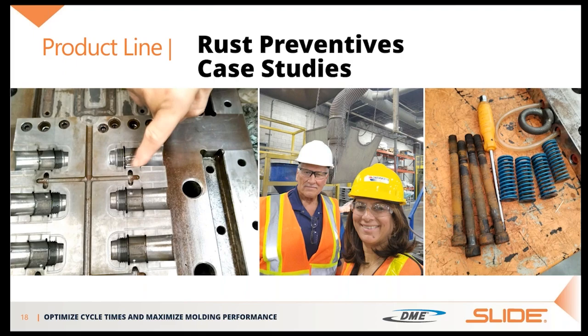So when applying the Quick RP rust preventive, just like the mold shield, you're just going to start at the top, 8 to 12 inches away, just an even coat. But with the Quick RP, you can see what you've hit, and a lot of times that's all you need, instead of having to use a real heavy duty rust preventive and then creating work later. So that was a really cool win, and that company buys a lot of that product from us in order to protect their molds, and they don't have any issues now.